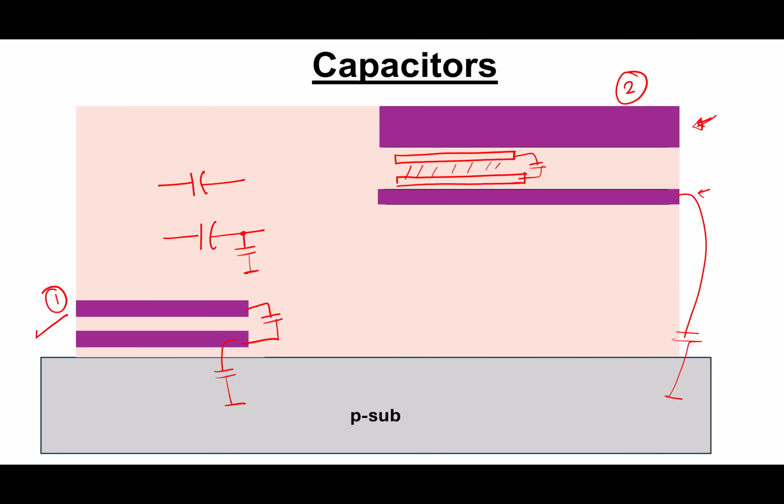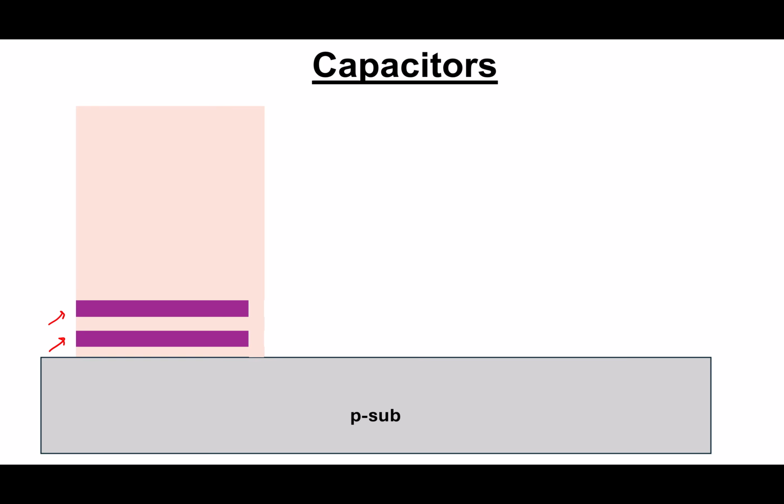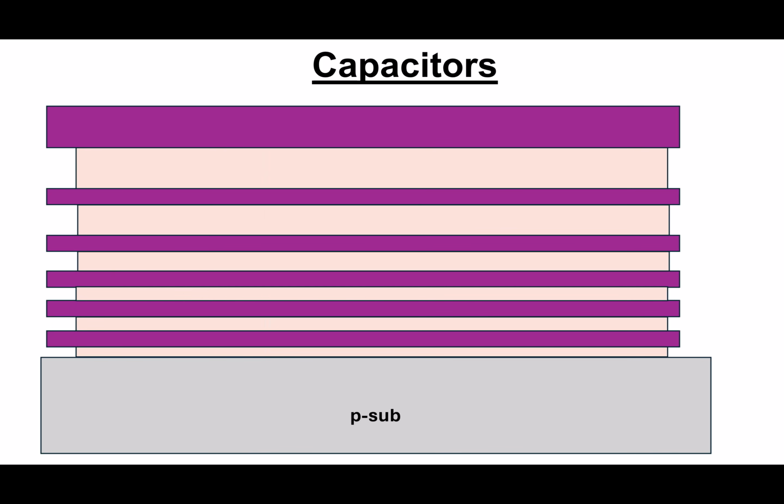Basically, here what is done is special. As I mentioned, different metals and different dielectrics will be used. What you are pointing out is correct. Let us say you are having things like this. There is also capacitance formed here. Those are unwanted capacitors, what we call parasitic capacitors. Just like parasites, they come and latch onto your design and affect you.